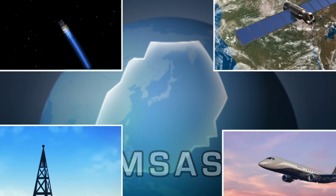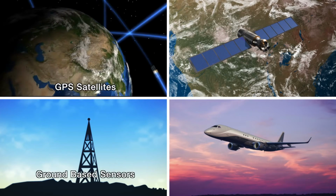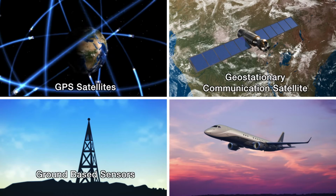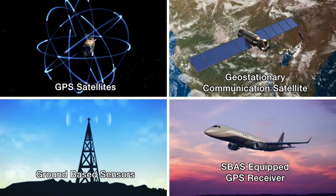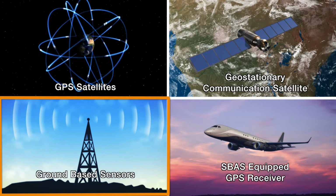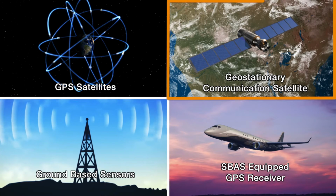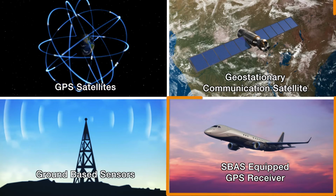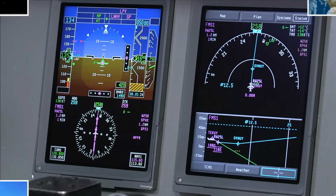An SBAS system is made up of GPS satellites, a network of ground-based sensors, space-based geostationary communications satellites, and SBAS-capable GPS receivers. The ground-based sensors gather GPS signals and apply a correction to them. The correction data is then sent to a geostationary communications satellite, which in turn broadcasts the information to an SBAS-equipped GPS receiver on board an aircraft.